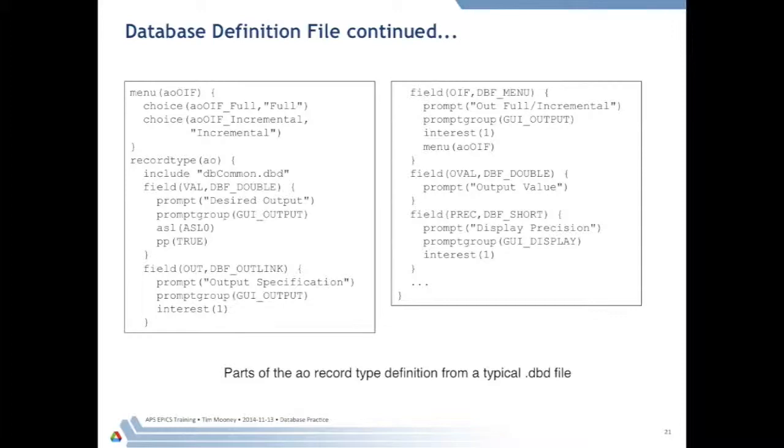So moving on, later in that file, here we get our first record type. This is the definition of an analog input record. And remember I was talking about fields common to all records? Every record, in order to be an EPICS record, has to have this in it, and it contains all of the fields that EPICS needs to be able to manipulate that record. The scan field, for example. All records have to have a scan field.